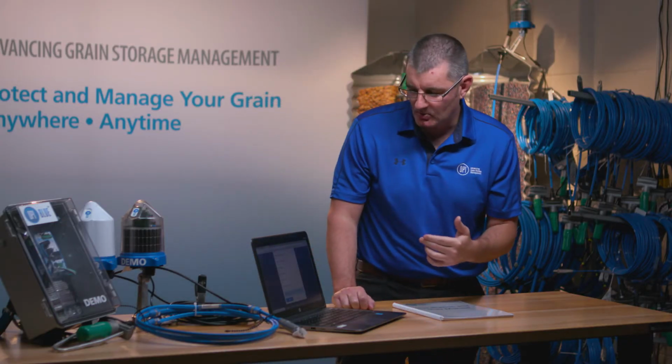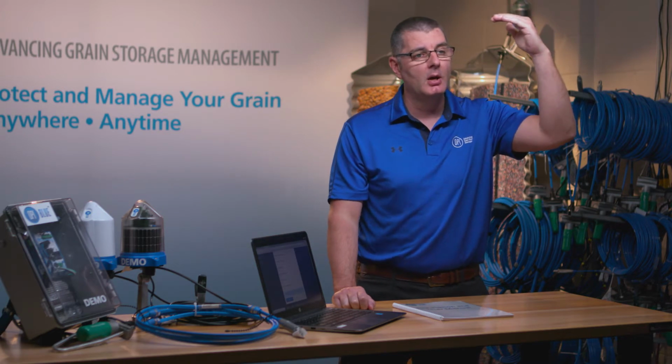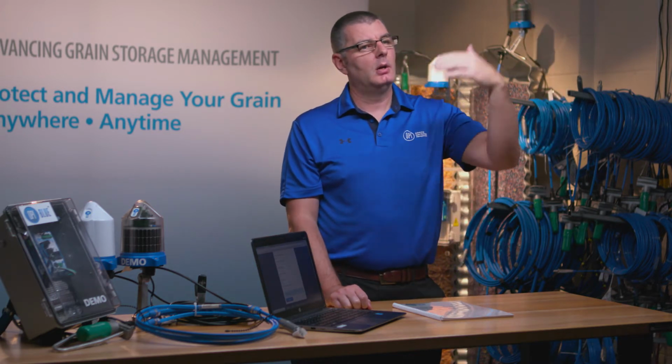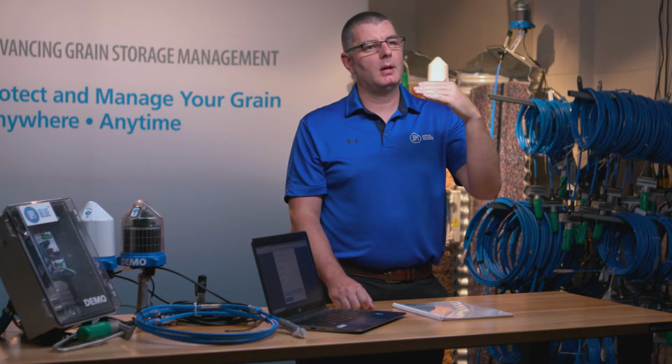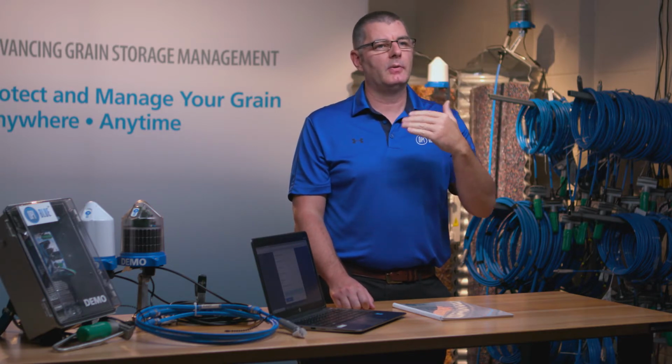So it's important that you have a reasonable set point in there as well. You don't want it set too high. If you've got it set too high, problems have already occurred. You want to set it low enough that if you do get the fans coming on, they're mitigating a potential problem before it becomes a full-blown problem.